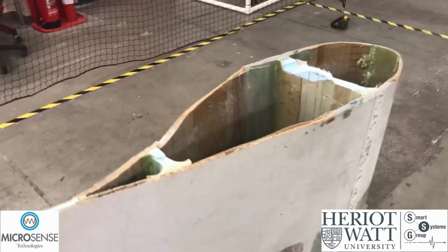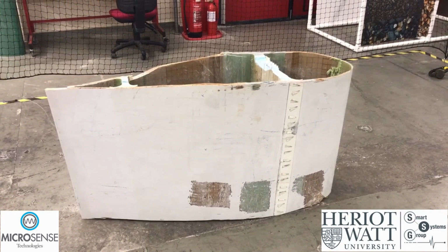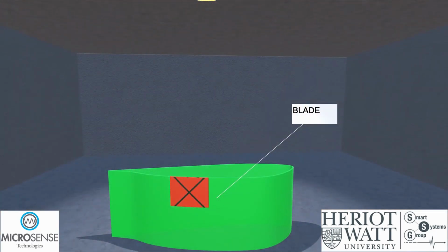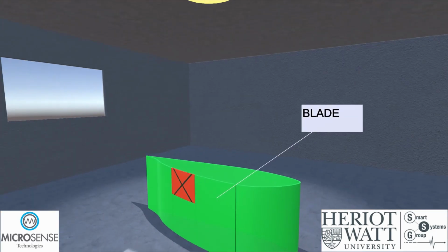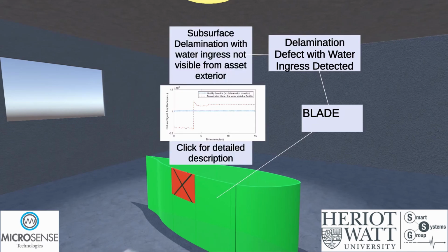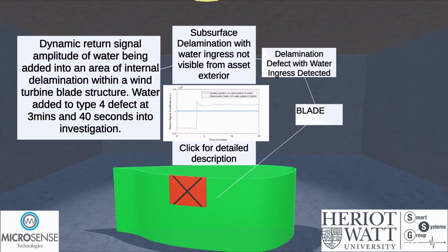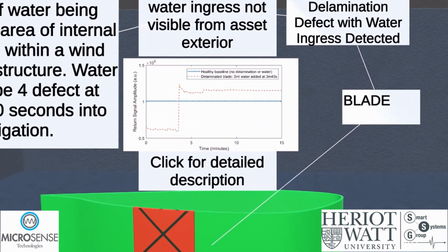The advantages offered to structural health monitoring practices for the renewables sector due to this inspection technique include a non-contact, standoff inspection method. The FMCW radar augments and complements current state-of-the-art sensing suites, which include visual and infrared cameras in defect detection strategies. Our sensor has been proven to detect internal defects which are attributed to the surface and subsurface properties of a wind turbine blade. These include the detection of operationally induced material failures and manufacturing defects.